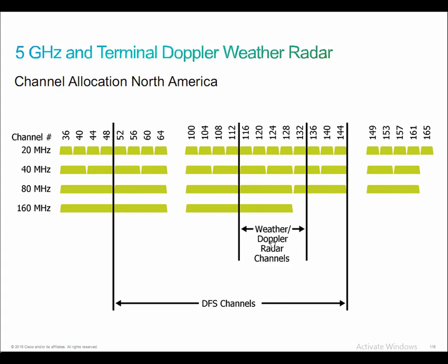So keep in mind, we're still going to affect those channels even though they're bonded together. And then we'll look for another part of the spectrum to set up a similar bonding scenario. If I can't find any clear spectrum space, I'll drop that whole segment of the spectrum and just won't use it. I might even go, say, from a 40 megahertz bond down to a 20 megahertz signal, or from an 80 megahertz bond down to a 40 megahertz signal. All right.